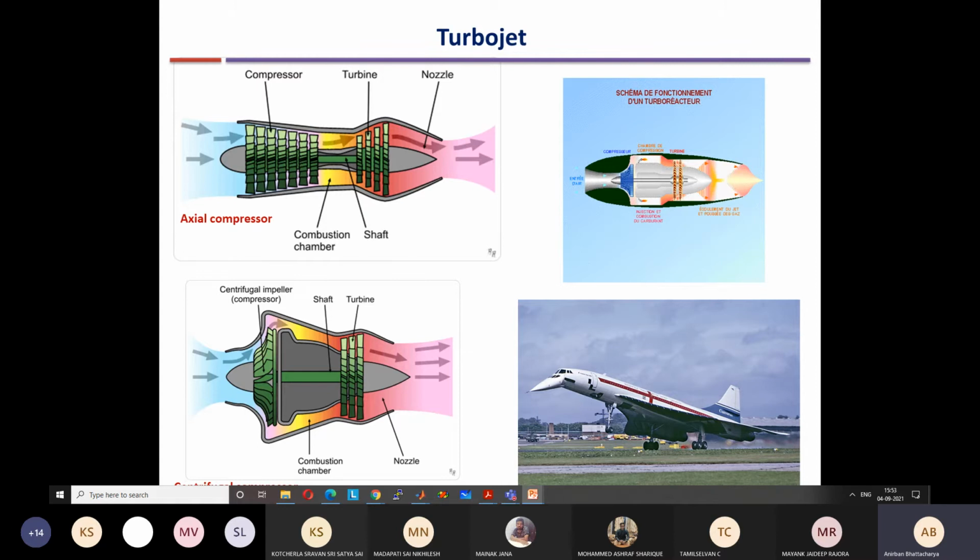For industrial gas turbines, the main things were important: the efficiency, the specific fuel consumption, which we calculated as the fuel consumption per unit work, and the net specific work output. For jet engines, efficiency is obviously still very important, but instead of work output, thrust is the more important factor. So what is the specific thrust or impulse? Specific thrust is known as impulse.